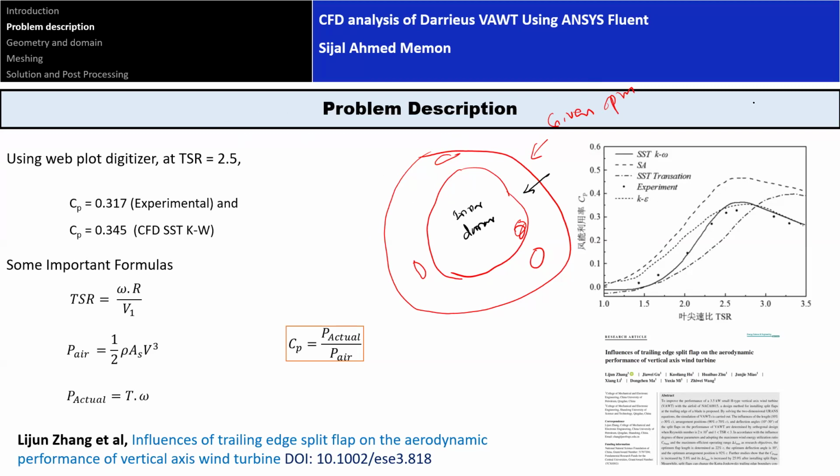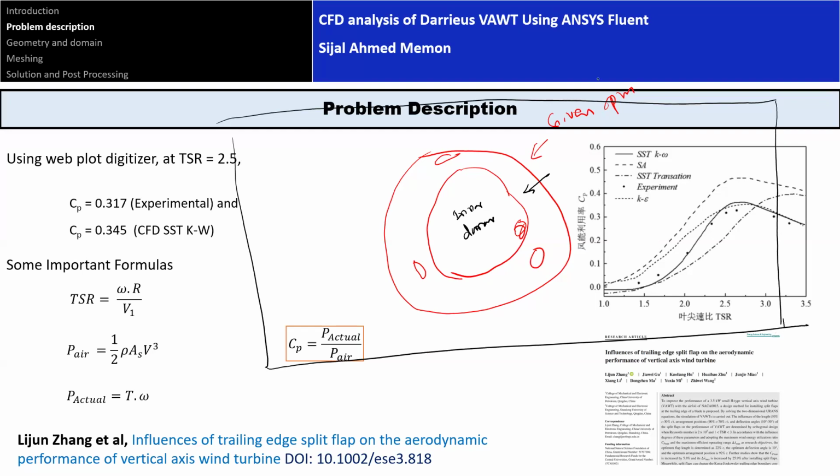And there will be an outside domain that will model the flow, that will be the atmospheric conditions. The domain size of the outside will take care of the atmospheric conditions in the vicinity of the wind turbine. The boundaries should be away from the wind turbine so that the conditions on them are the same as atmospheric conditions and do not get disturbed by the presence of the wind turbine. They should be large enough to ensure that atmospheric conditions are present everywhere on the domain.